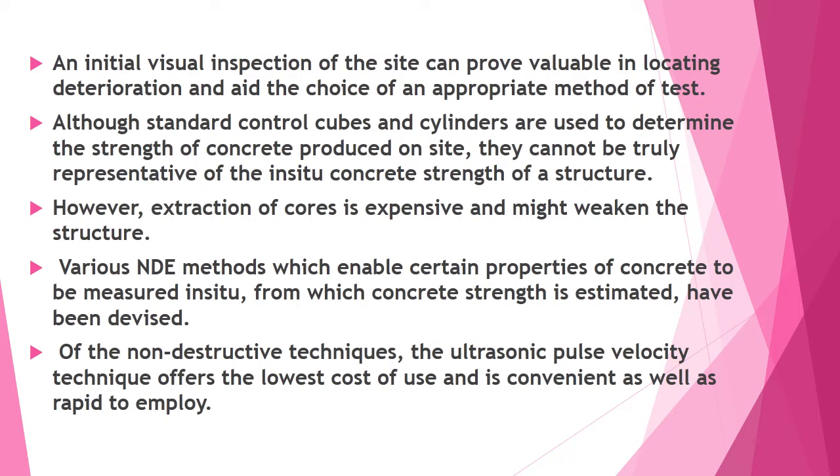Although standard control cubes and cylinders are used to determine the strength of the concrete, they cannot be truly representative of the in situ concrete strength of a structure. However, extraction of cores is expensive and might weaken the structure. Various NDE methods, which enable certain properties of concrete to be measured in situ, from which concrete strength is estimated, have been devised. Of the non-destructive techniques, the ultrasonic pulse velocity technique offers the lowest cost and is convenient as well as rapid to employ.